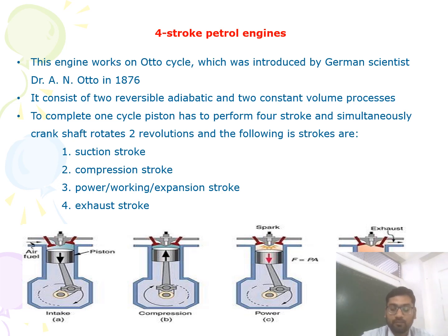As the piston moves from TDC to BDC, the pressure of the hot gases gradually decreases and the volume increases. This is represented by the 3 to 4 line in the PV diagram. Near the end of the stroke, the exhaust valve opens. So all these burnt gases or exhaust gases seep out to the atmosphere, and this suddenly brings the cylinder pressure to atmospheric pressure, and this constant volume drop of pressure is represented by the 4 to 1 line in the PV diagram.